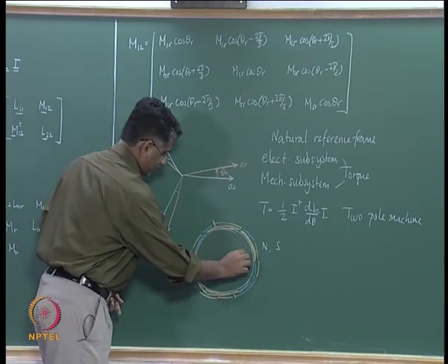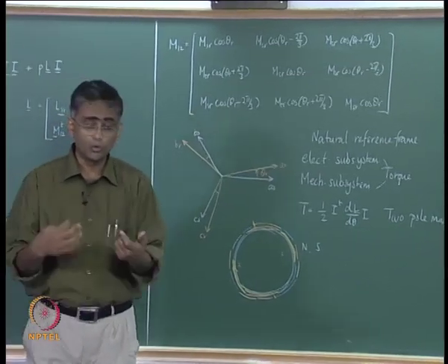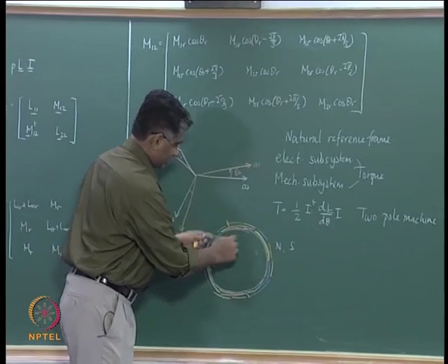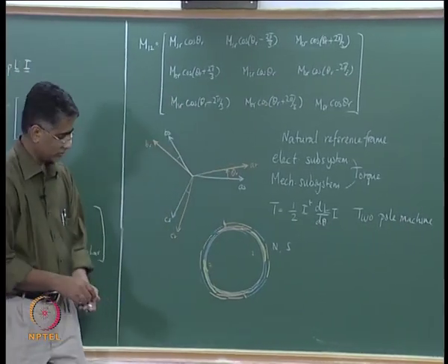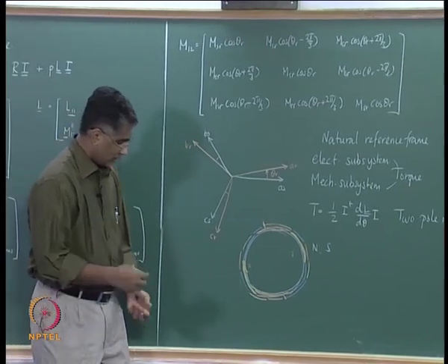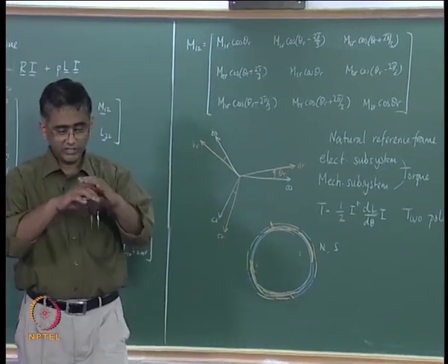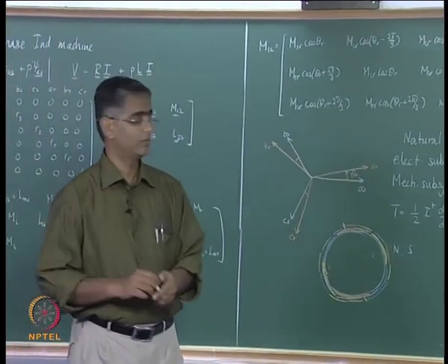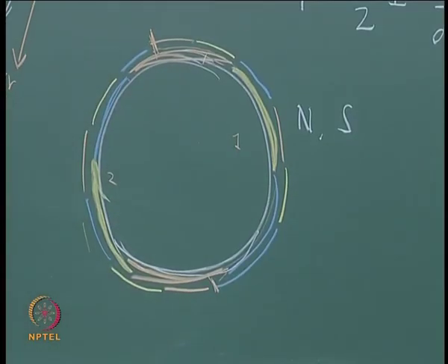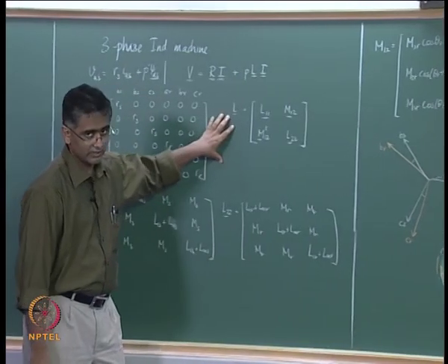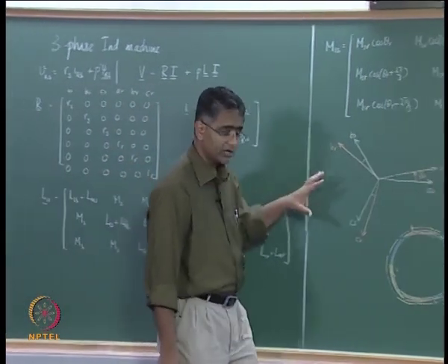Here you have the first cycle and here you are having the second cycle. If you are going to have more poles, then you need to shorten this, then you will have 1, 2, 3 and 4 pole structure, and so on. And therefore, since it is sufficient to look at one cycle or the space enclosed by one cycle of the MMF waveform, what we analyze is then a two pole equivalent, and the behavior will be the same.